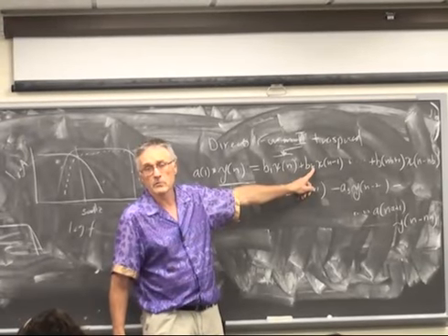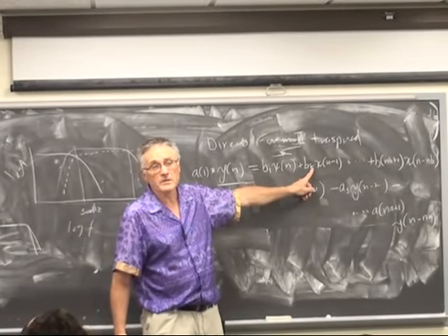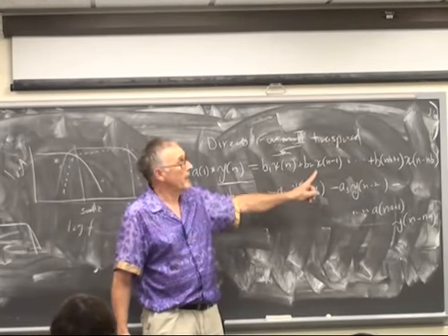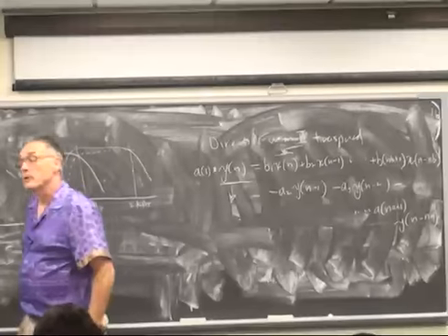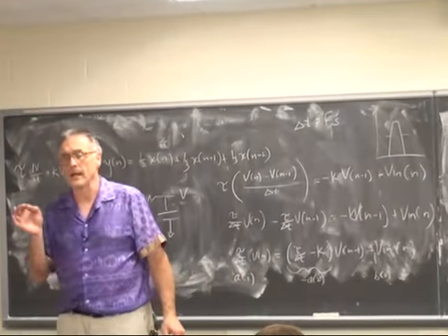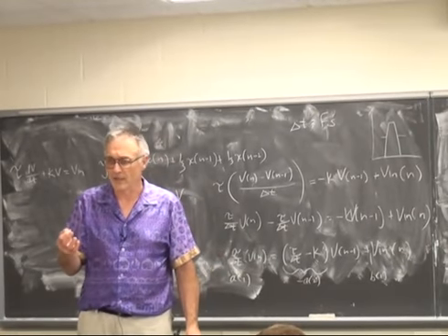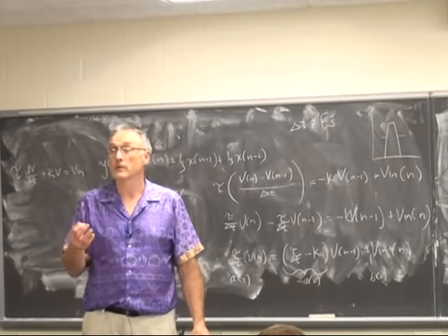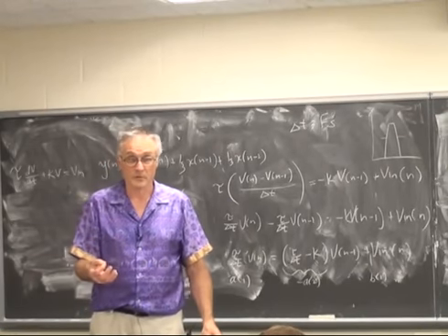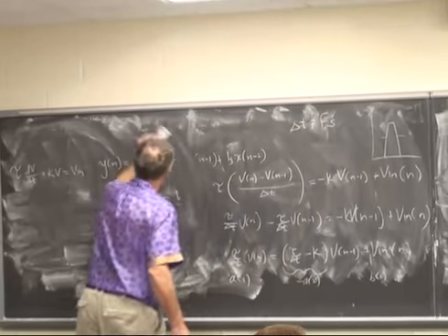And then instead of getting a small answer, you'll get a 0. Something won't cancel correctly. You'll get a 0 where you should get some cancellation. And the filter won't operate properly. So you're going to have to worry quite a lot in this lab about finite bit approximations, finite word length approximations of digital filters. So when you design your filters, and by the way, I would say the best way to do that